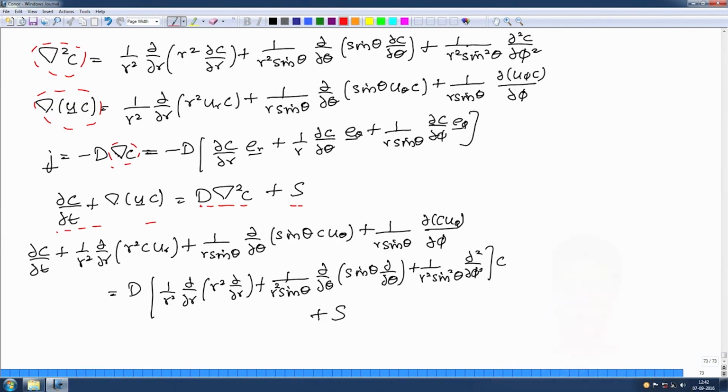We will start looking at diffusion dominated flows in the next lecture, where we can neglect the convective terms. The solution of the Laplace equation in most cases is done by separation of variables. I had shown you previously how to do separation of variables in the Cartesian coordinate in one direction. In 3 directions, the procedure is very similar. I had shown you how to do it in a cylindrical coordinate system. In this series of lectures, I will show you how to do it in a spherical coordinate system.